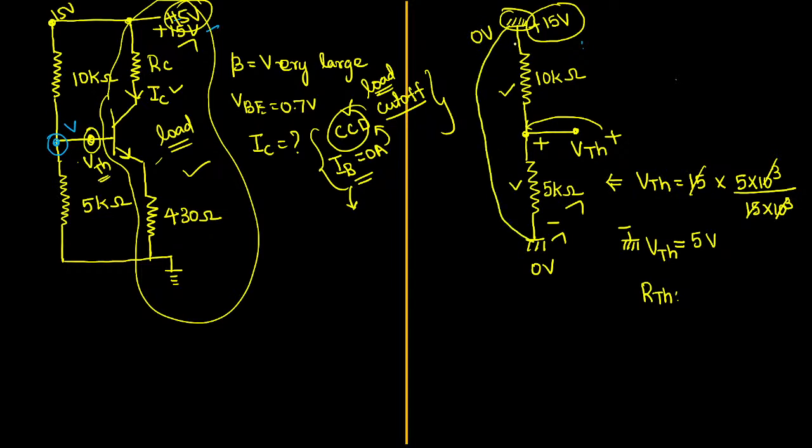So what you can do is just fold this resistor. Folding in the sense, if you connect this ground as one, then shall I draw the resistor like this? It will come like this everywhere. I have just folded that resistor below, that's all. I am connecting to the ground. This is 10 kilo ohm, this is 5 kilo ohm. From where are we calculating the RTH? From here. This is going to be our RTH zone.